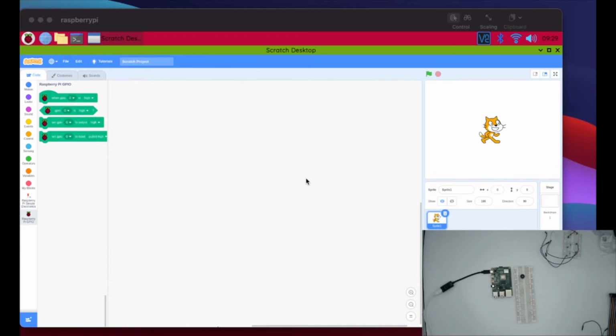So I'm going to go ahead here and get this wired in. In this case, I'm going to use brown for my ground, which is the negative. Remember, these things run horizontal here, so I know I'm in row 13. There's 10, 11, 12, there we go, 13. And I know my ground, if you remember from yesterday, is the 3rd GPIO pin down from the right column of the Raspberry Pi. Remember, the first 2 are both 5 volts, and we don't want to do that.